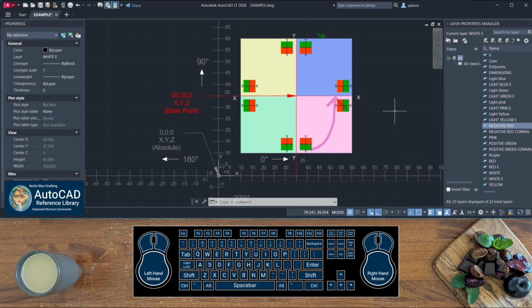When creating rectangles or squares, you will notice a matrix within these quadrants. The green area indicates positive values to be entered, while the red area signifies negative values. The position of the crosshairs within these quadrants determines the direction and sign, positive or negative, of the X and Y values and where the shape will eventuate.